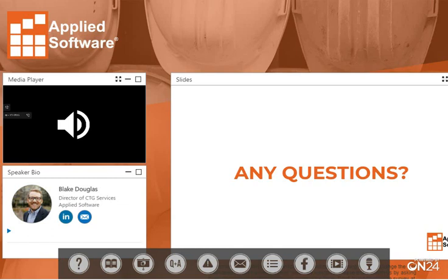You have the ability to link that Revit file within the other company's hub. So what you would do with Bridge is bring it to your own environment, and then you can operate like you would if you owned it in your own environment anyway. There are some caveats there. You have to have permission, if you will, from the other hub. So you can't just go in and grab it. They have to allow or grant access. So there is a little bit of checks and balances there as it relates to permission, but we can discuss that in further detail as well.